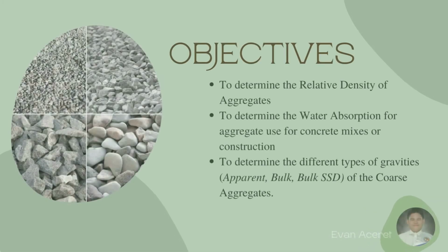First is to determine the relative density of aggregates. Second, to determine the water absorption for aggregate use for concrete mixes or construction. And lastly, to determine the different types of gravities, apparent, bulk, and bulk SSD of the coarse aggregate.